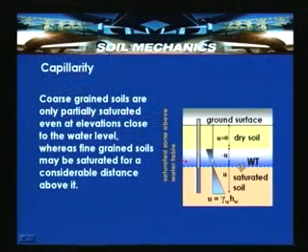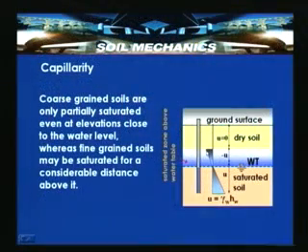So, the water above the water table is under tension, which is called capillary tension, and below is positive pore water pressure. Above this, if there is a partially saturated soil, the distribution of the pore water pressure can have a certain reduced pressure. But if a dry soil comes immediately, where the capillary raise is almost negligible, in that case it can run like this, a negative pressure.